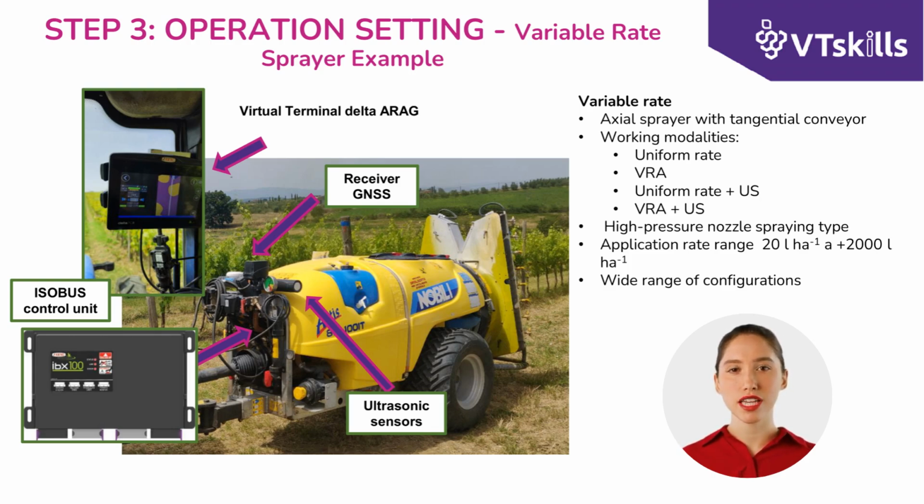These machines, which can also be used in traditional mode with constant volume spraying per hectare, require an adjustment of the number of nozzles operated during the season, which must be selected to cover the entire vegetative strip, avoiding upward and downward dispersions. For machines equipped with swiveling conveyors, it is necessary to adjust the inclination so that the air and mixture jet are directed exclusively at the foliage. VRA machines also offer the advantage of being able to track the work done by the machine, thus monitoring the quantities that were actually distributed during spraying.